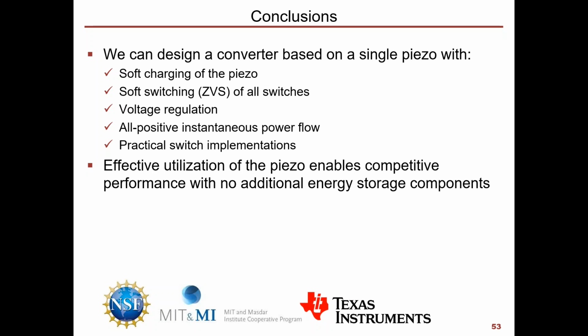So with that, we can conclude that we can design a converter based on a single piezo with all of the high efficiency behaviors we've discussed, like soft charging, zero voltage switching, voltage regulation, and all positive instantaneous power flow. And we can do this with practical switch implementations. And that's what's going to help make these competitive against other types of converters. Now, the take-home point here is that it's actually the effective utilization of this piezo, meaning all of these behaviors together, that enables the competitive performance with no additional energy storage components.